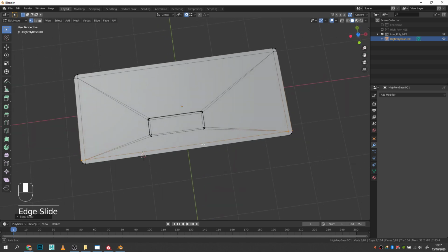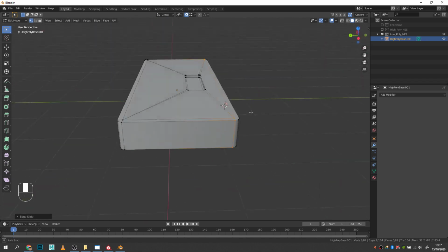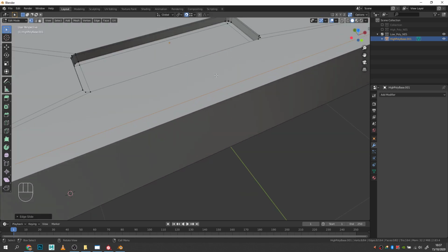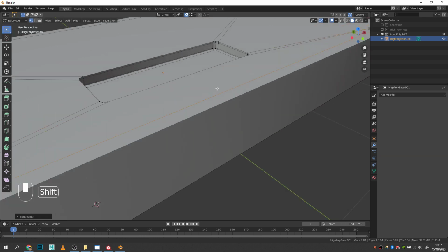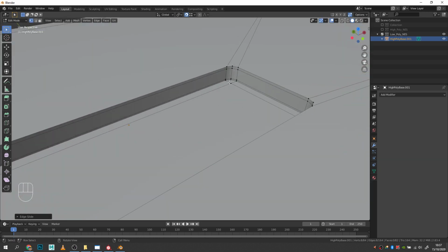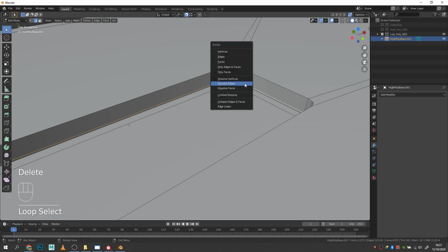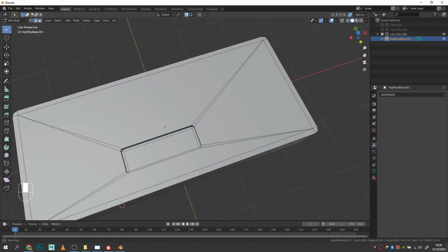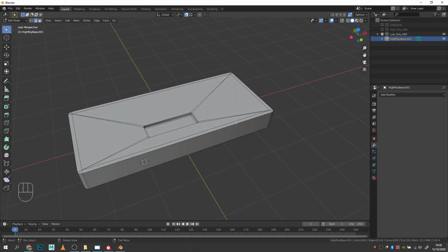So there we've got a much lower poly asset. In fact, you can see the number of tris that we've got down here, so 164. There's still more we can get rid of, so there's still edges in here that we don't need. So 2 on the keyboard, this edge for example, delete I, this edge for example, delete I. That's about as low as we're going to go. So there's our low poly, ready to rock and roll. We should probably rename that.